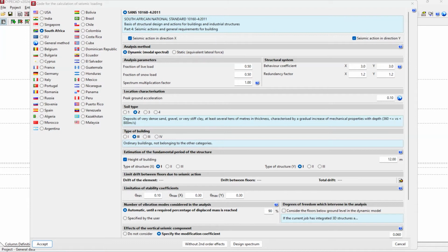If we just concentrate on the brickwork, you do your single-story brickwork, then you do your roof, sometimes you have still not solved the issue of seismic loading, because you don't have columns which can resist earthquakes. You have load-bearing walls, the walls that are actually bearing the whole load. That's what is happening, correct?